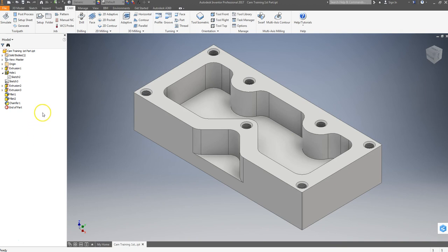And speaking of features, some people like to do holes. They just make a circle and then they cut it down. And it does achieve that. But if I were to make a working drawing, top, front, right side view, and dimension it, and have hole callouts and all that stuff, I won't get any of the detail information. Like this is a tapped hole. It's drilled a certain depth, it's tapped a certain depth, it has a countersink on top of it. Or if I have a hole that has a counter bore or something along those lines, I don't get that information. And so when I make my working drawings, I have to type all that in instead of getting it for free. I like free.